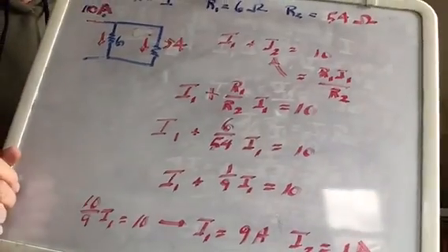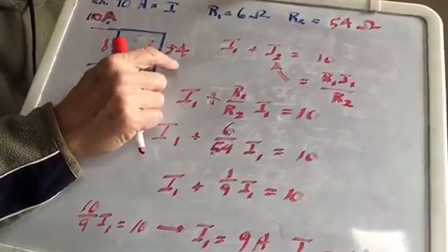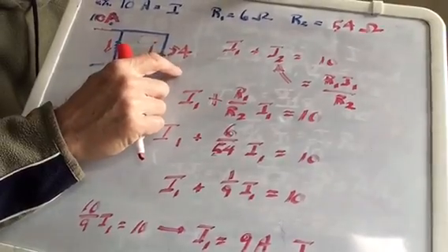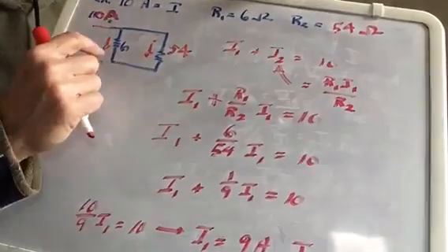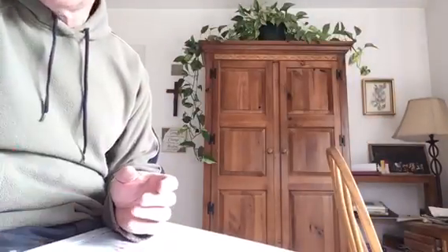All right. So hopefully it just makes sense now with this current splitter. The larger we make this second resistance, the more current goes to the other resistor. And there's mathematics behind it so that we can solve it and work it out exactly. Okay, what does that have to do with PV?